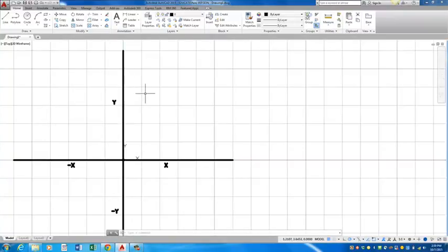Hello, this video is to show you the difference between absolute and relative coordinate systems. For this video I'm going to show you how to use Cartesian coordinates, which you should have learned previously in your schooling, or you may be learning it for the first time now. But there's two different ways to use it when you're doing G-code programming, which we're going to be doing real soon after this video. To explain it the best, our Cartesian coordinate systems can be broken up into four quadrants.